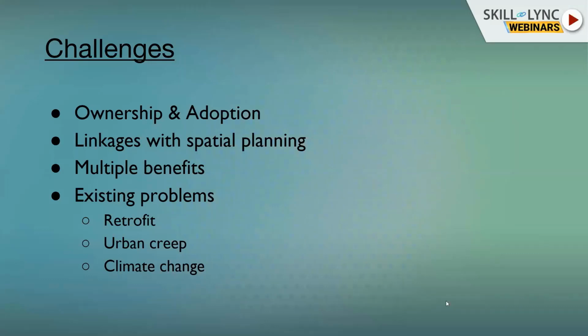The next one is the urban creep. Even if we have designed a SuDS element, let's say in the example of the case study, we took a climate change factor of 20%. Sometimes it will be 40%, and currently in some parts of Europe, they consider a factor of 40%. So if the rainfall increases, then we have to redo these SuDS components. Urban creep is like in a township, there are 10 houses, then 5 more come up. It will increase the surface flow. Then we have to think about expanding the SuDS element. And then the climate change was also discussed.